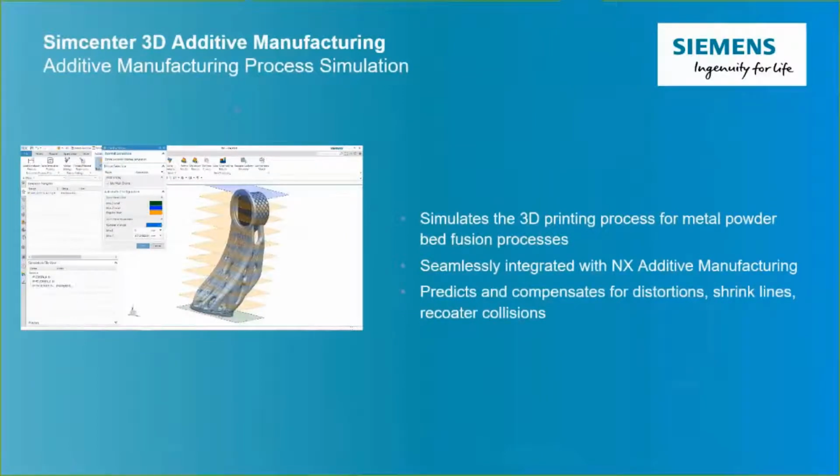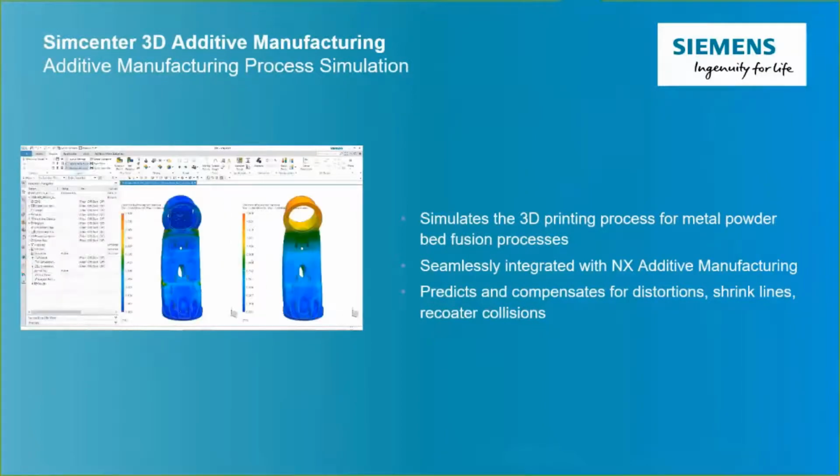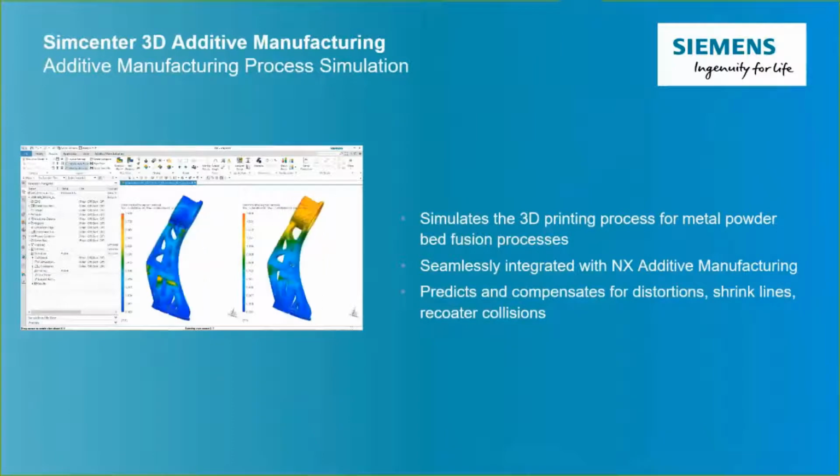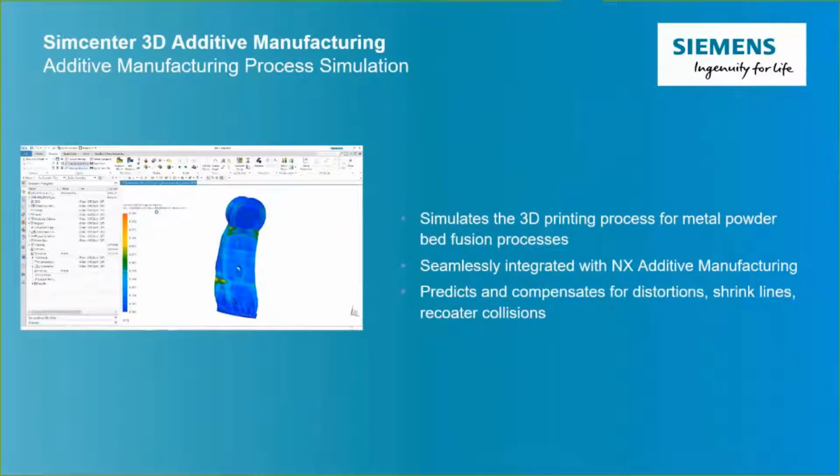So just to review, SimCenter 3D Additive Manufacturing is embedded in the NX Additive Manufacturing Framework. It's launched from the build preparation step in NX, and it provides a streamlined workflow to easily define the simulation of the build process. It's able to simulate temperature with and without powder, simulate the probability of overheating, predict distortion before supports, after heat treatment, and as built. It can generate compensated geometry to mitigate distortion. It can predict the occurrence of shrink lines, and it can predict and warn about recoater collisions.